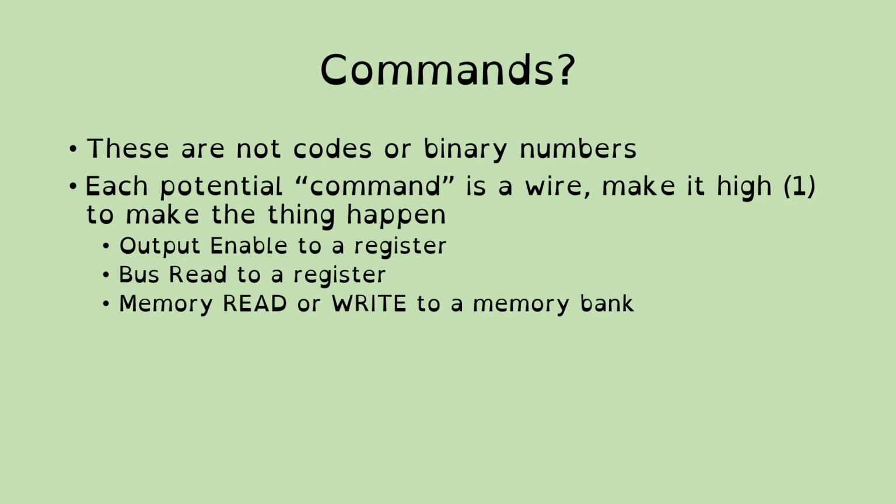Memory read or write to a memory bank. If you've been through the stuff with the memory bank that we created, you'll hopefully remember that as well as putting the information into the data register and the address register, you also need to do a read or a write to actually get that into the memory bank or out of the memory bank. Execute to the ALU.